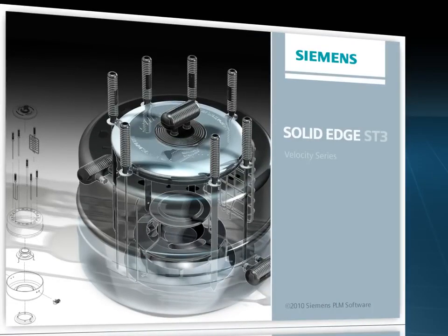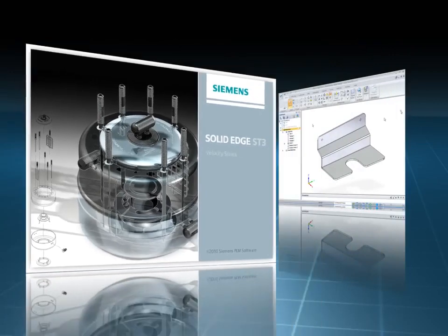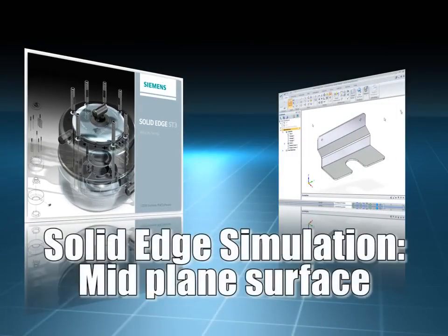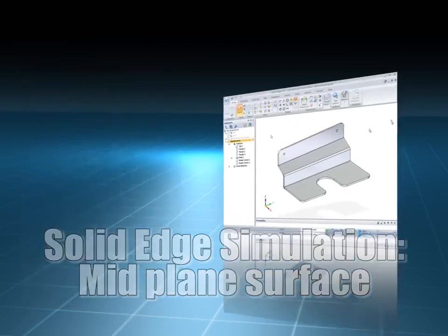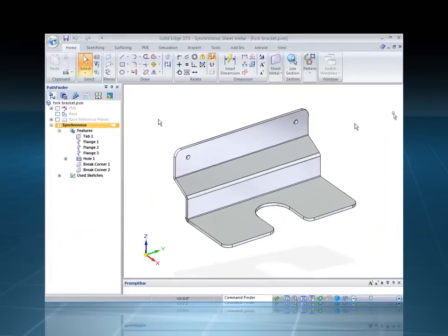In this week's show, I'm joined by Mark Thompson, who will show you how to extract a mid-plane surface in Solid Edge simulation and then mesh it with surface elements. To mesh a part like this with solid elements would require a larger model to attain any degree of accuracy. By creating a shell element model, a high degree of accuracy can be obtained, with fewer elements producing a much smaller and more efficient model. Let's see how it's done, Mark.